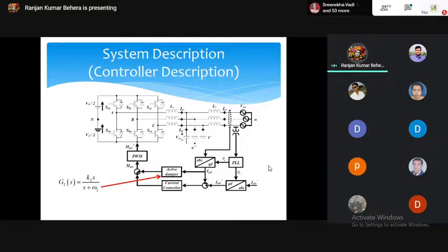Similarly, in a dynamic system, when you have a dynamic in the voltage or a dynamic in the change, you need to produce another dynamic which can compensate that one. And that is called this parallel active damper. Even the current controller has no capability to decouple the thing, whereas the active damper helps us to decouple it. And that is the closed loop: PLL, then ABC to DQ transformation, then current control, then active damper, then PWM, then switching.